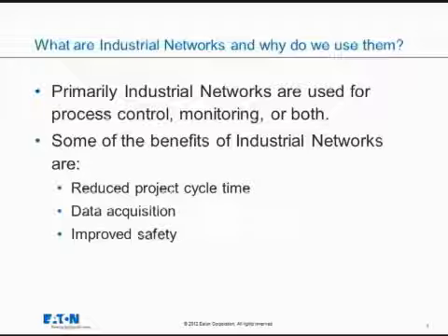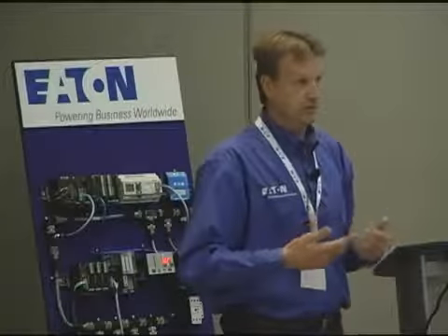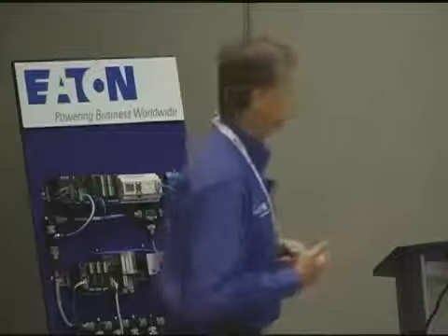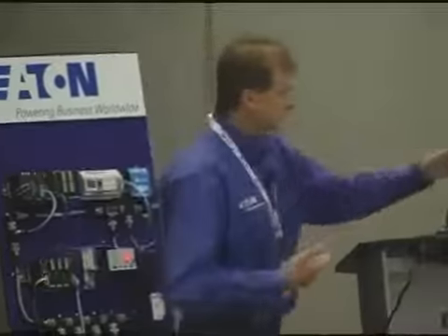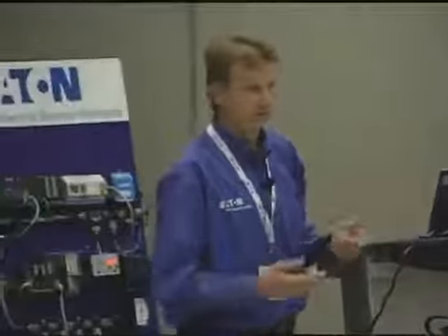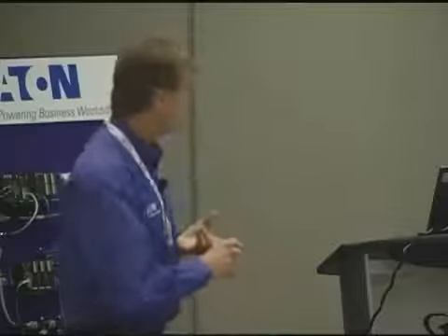Improve safety. With networking, now you can troubleshoot. You don't have to stand in front of the equipment. It's a lot safer now. You can do a lot of troubleshooting over a network. You could be standing, like we have an HMI on that board, and you could do a lot of troubleshooting right from there if you tie all the signals back. Signals like your fault log, things like that. You can see what's been going on.